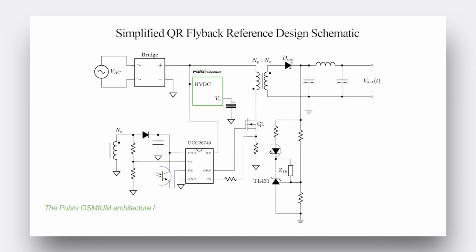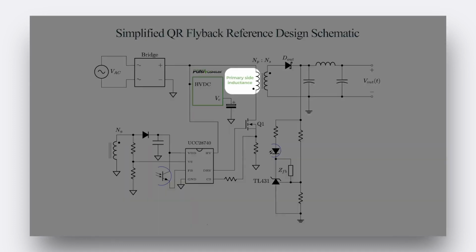For power levels up to 150 watts, conventional quasi-resonant flyback controllers can be used. There are some excellent guides on how to design flyback converters provided by power supply controller manufacturers, and this guide is not intended to replace these. This guide is primarily to provide clarity on specifying the primary side inductance needed for discontinuous conduction mode, after which the design of the flyback can be completed using the documentation from the manufacturer.